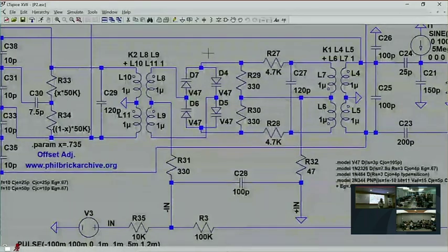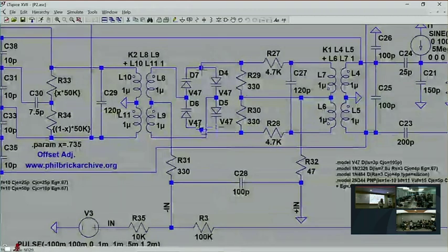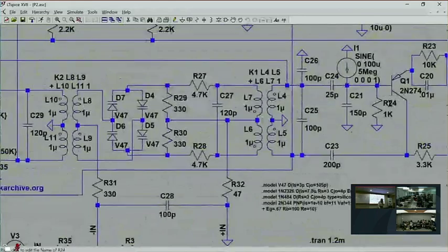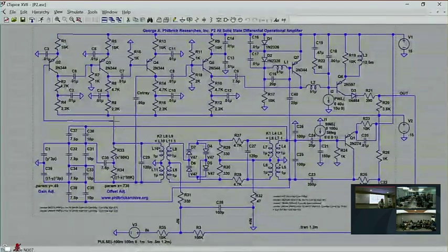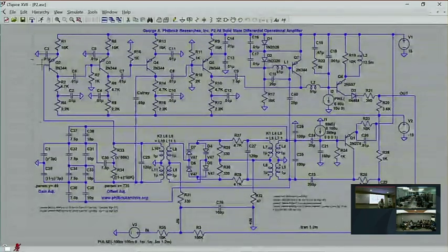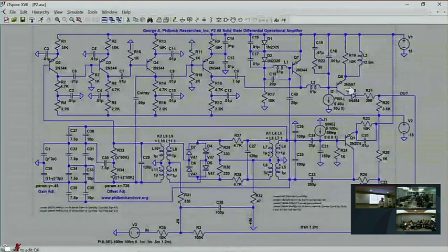These input signals would meander around to this varactor ring. This varactor ring was a mixer, parametric up conversion. The inverting input would come around to this node and that node. The non-inverting input would come to that node, and this varactor ring was pumped with this local oscillator. So if there was an input signal, you would get an output at the local oscillator frequency that would come out here, amplified by this IF strip, synchronous detection here, and a single transistor baseband gain. That was the way it was implemented.